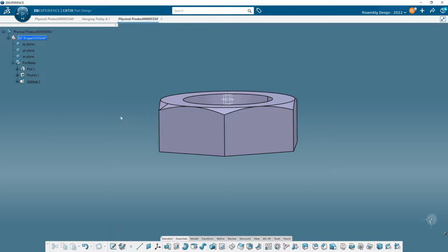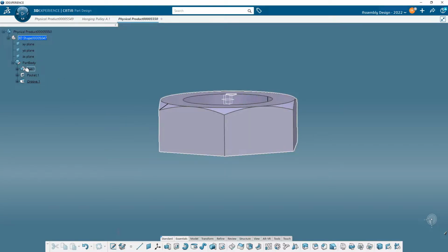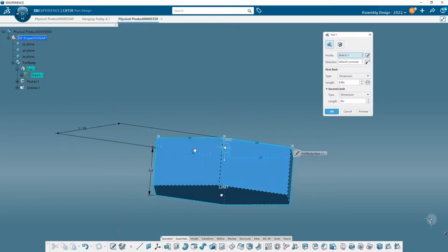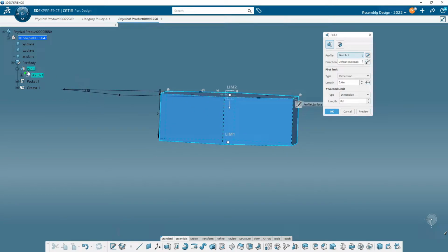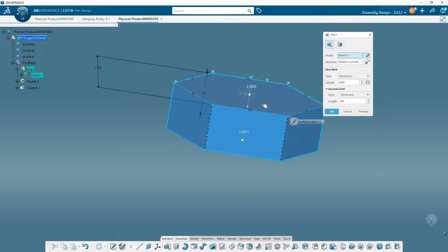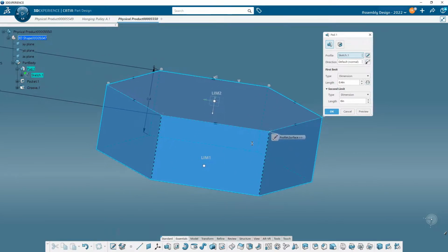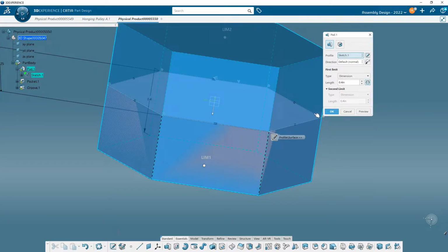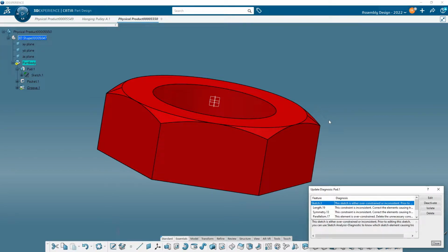So what did I do here? Well, the first thing was this pad. So let's double click on this, and it goes back in time to when we made the pad, and you can see it's 0.4 across that plane. So this is a simple edit, right? It's 0.4. And here's my symmetrical button right here. So I hit this and now it's 0.4 in both directions. Well, I'll just simply change that to 0.2. Hit OK. And now you end up with a couple small problems, right?